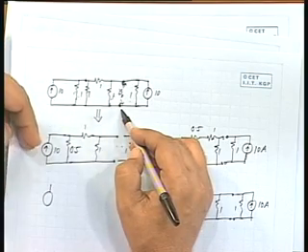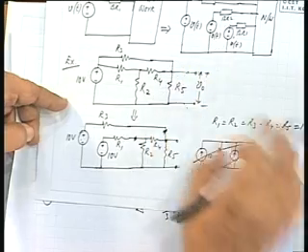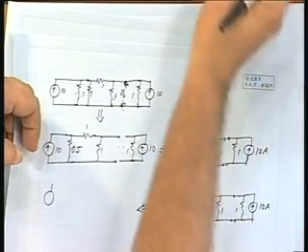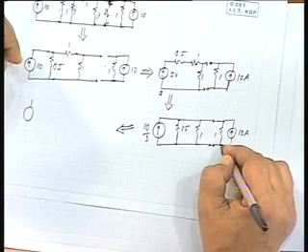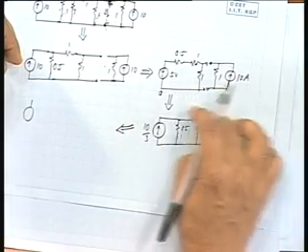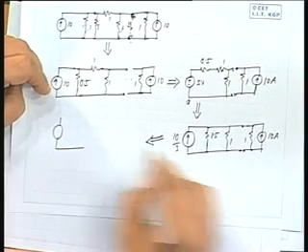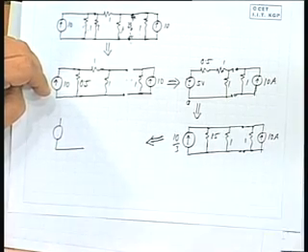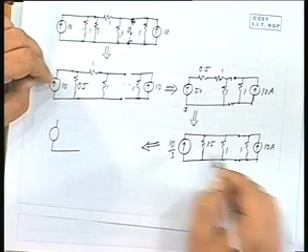Okay. So, that has not been disturbed here. I have just replaced this voltage source, but I have not replaced R5 so far. So, the voltage across R5 is the same as the voltage across this entire combination now. So, how much is this? 10 by 3 and 10, two sources together will be 13.33, this is 3.33 plus 10.